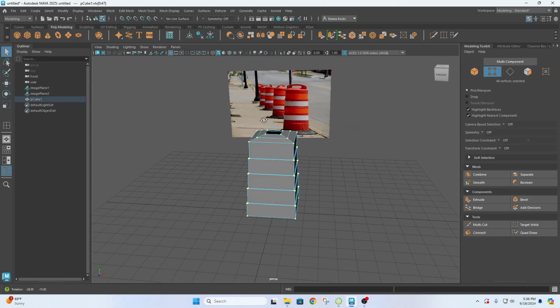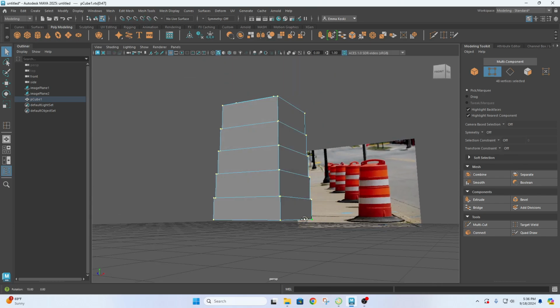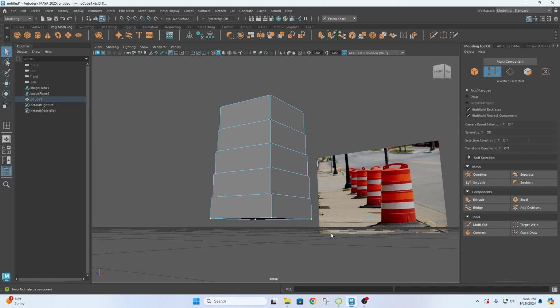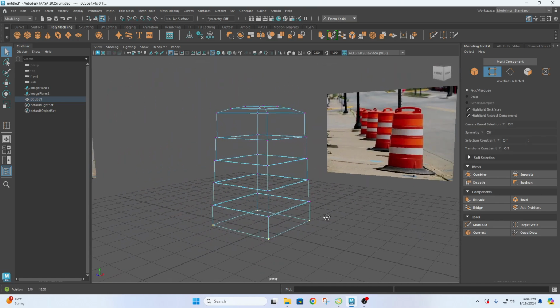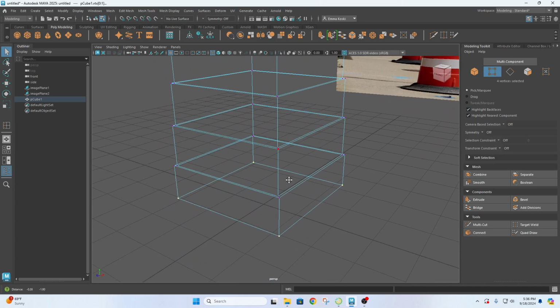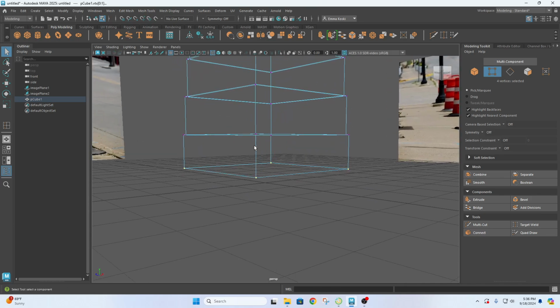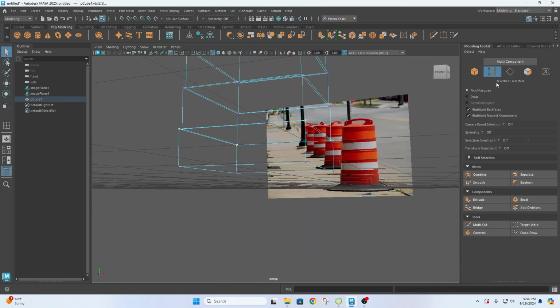So what you're going to do is try and clean up your object and find out where the issue is. You can do this by going row by row and hitting wireframe mode and making sure visually I only have 4 vertices selected, and it says 4 vertices here, so that's good. If I select the next layer up, I should have 8 vertices selected because visually I have 8, and it says 8 over here, that's good.